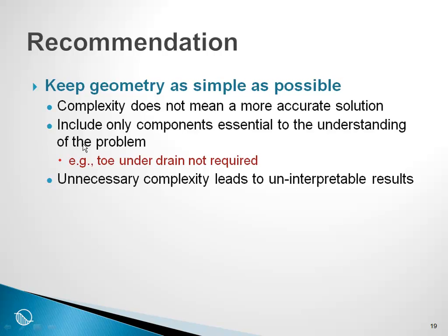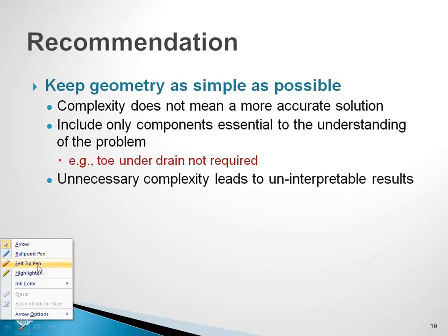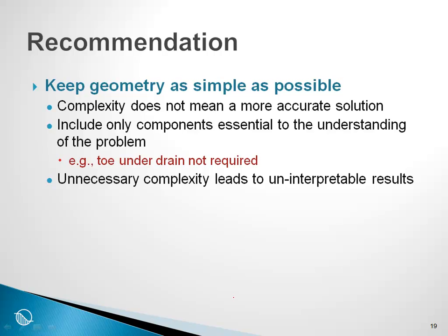Secondly, we suggest you include only components essential to the understanding of the problem. Notice that in our particular case that we were just working on, we did not include this under toe drain here. The toe drain does nothing toward dissipating the potential energy, therefore it is not necessary to include it.